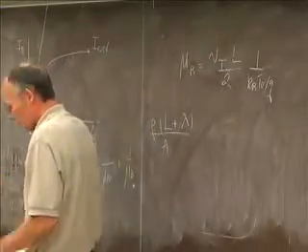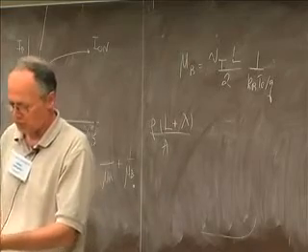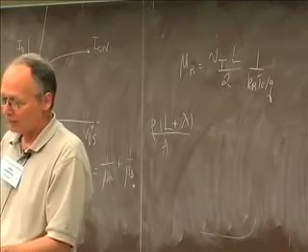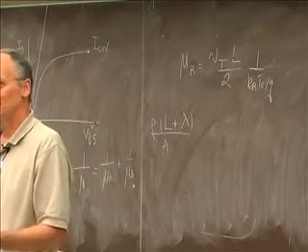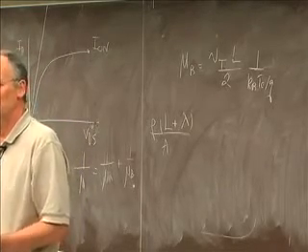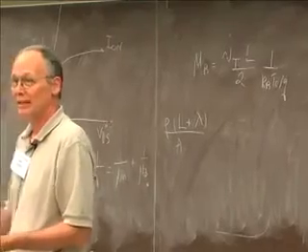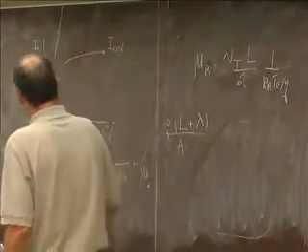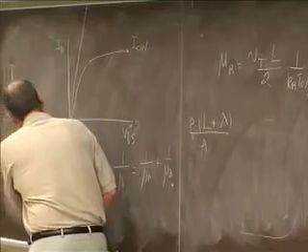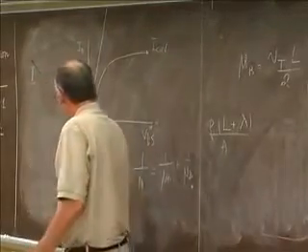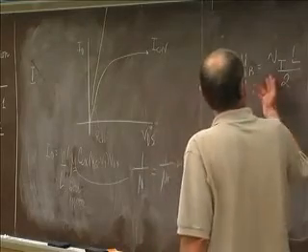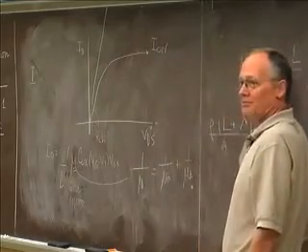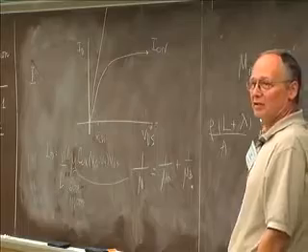Okay. But there is this advantage, alluded to in the second question. Is it that we can get the same current levels at longer channel lengths? Yes. So with relaxed geometry, especially if you're looking at RF devices, you can get very high performance. Oops, this should be W over L. I can go to much higher channel lengths where the ballistic mobility is bigger, so it doesn't limit things as much.